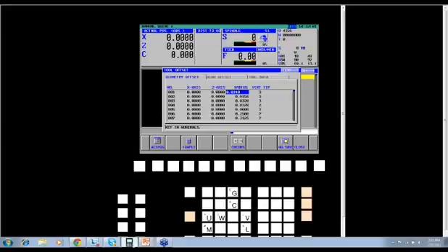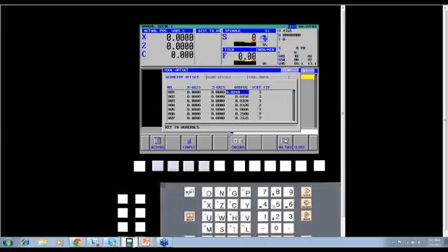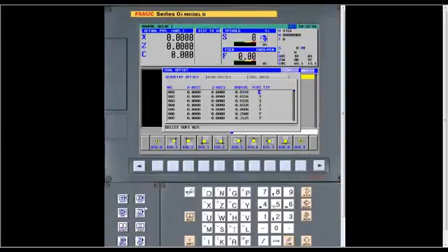The next one's very important also, the virtual tip, because what that's used for is the orientation of the tool. The ones you're going to use the most: a number 3 is typically going to be an OD turning tool, a number 2 will be an ID boring bar, and a number 7 will be a drill. Those are going to be the three that you use the most. That's what you see on this first page, tools 1 through 7: we have a 3, 3, 3, 2, a 3, and then 2, 7. So typically that's what you want there.